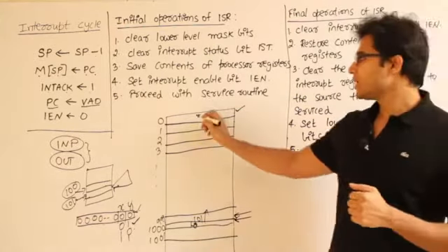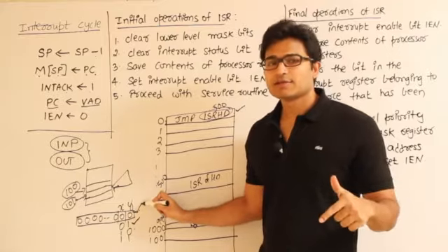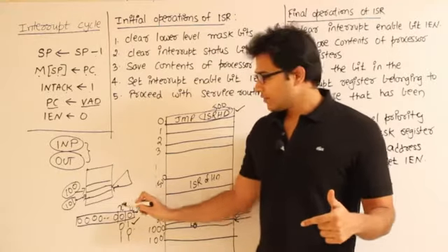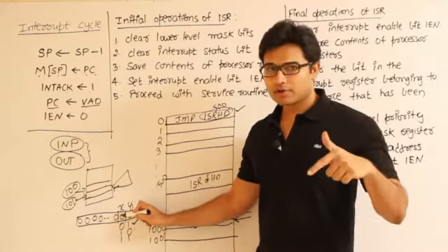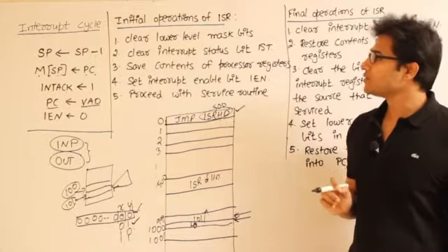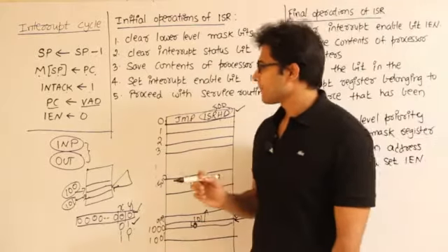So whenever an interrupt is raised by the hard disk, automatically the address will be provided by the encoder. That is why it is called vectored addressing, right? Vectored interrupt, which means the interrupting device is also providing you with the address. Now this address will be stored in the program counter, and so the program counter will start from the next instruction starting at this particular address, and when it goes to this address, it will understand that, oh, I have to jump to this particular address. Got it?